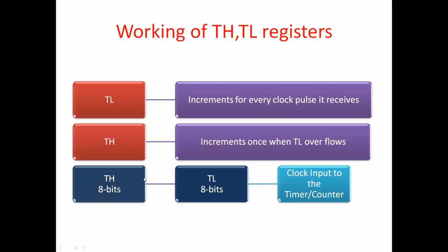For example, here 8 bits are used, so it can count from 0 to FF. In this TL, we can only adjust a value between 5 zeros and 5 ones. Between that, you can have any value. And this total count will be counted this many number of times. This into this, which is nothing but scaling. So that's why it is an 8-bit counter with 5-bit prescale.